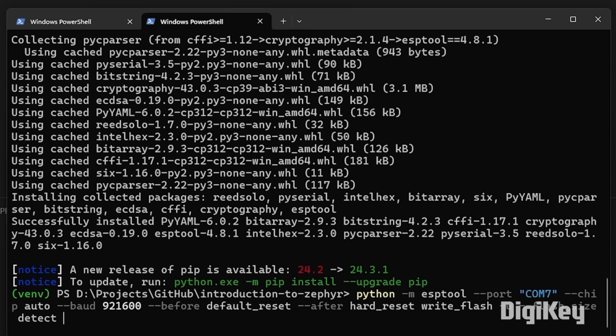And then we specify a starting address, which is hex 0. That's the very start of flash memory. If you have something like a second stage bootloader or you want to fire up the Wi-Fi drivers, that may be a different thing that we put here. And then it says, oh, go ahead and start the code in the application CPU. But because we're not doing that, we don't have that next bootloader where it starts firing up those drivers. We're just going to write our application directly to the Pro CPU flash and just start it from hex 0 right here. Then we're going to specify the binary.